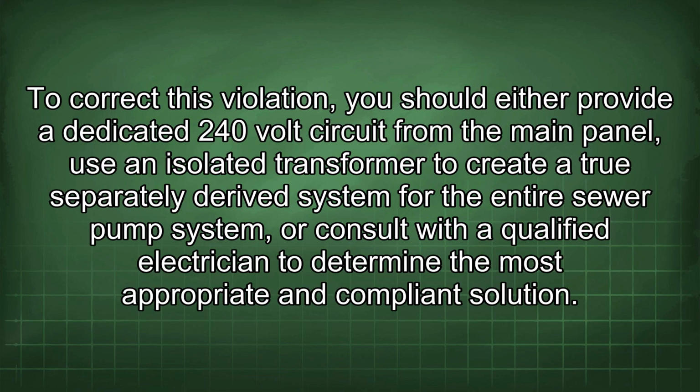To correct this violation, you should either provide a dedicated 240-volt circuit from the main panel, use an isolated transformer to create a true separately derived system for the entire sewer pump system, or consult with a qualified electrician to determine the most appropriate and compliant solution.